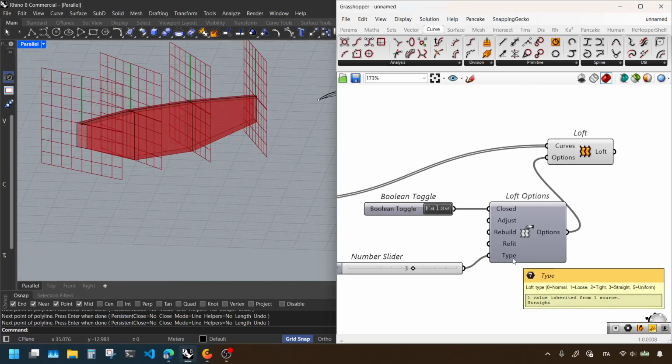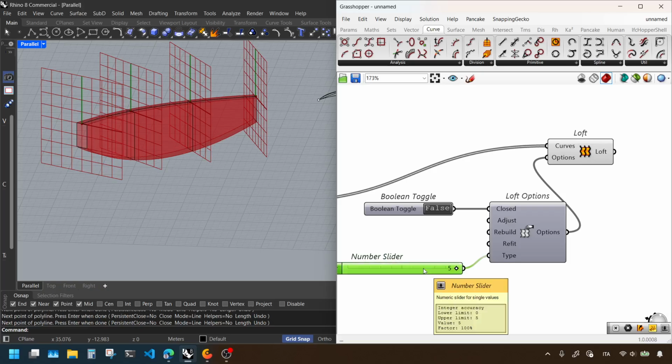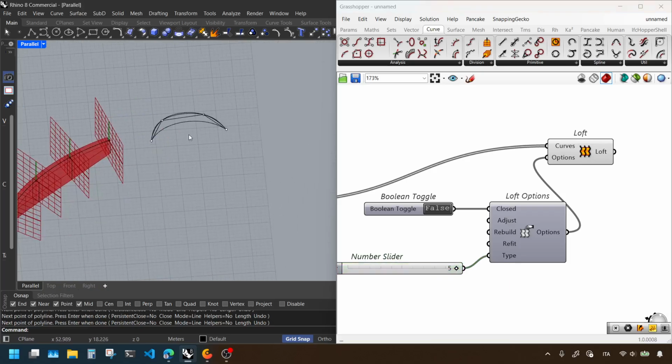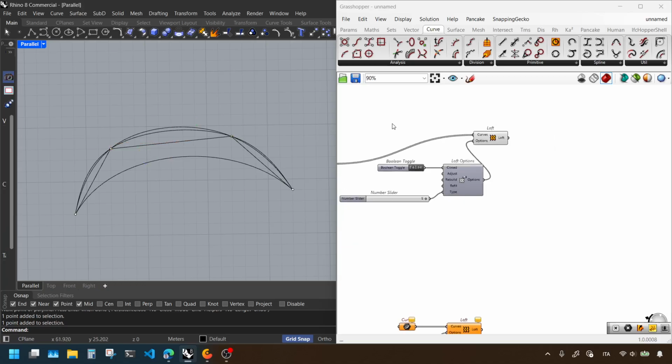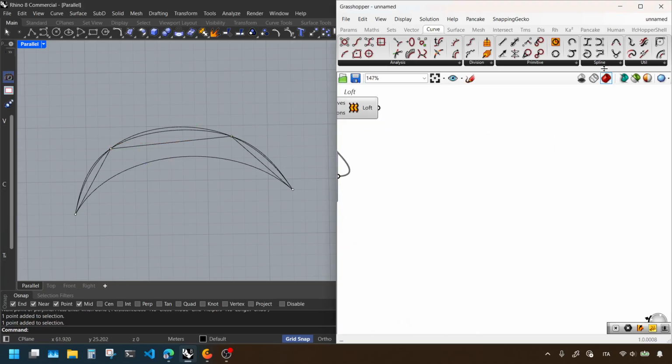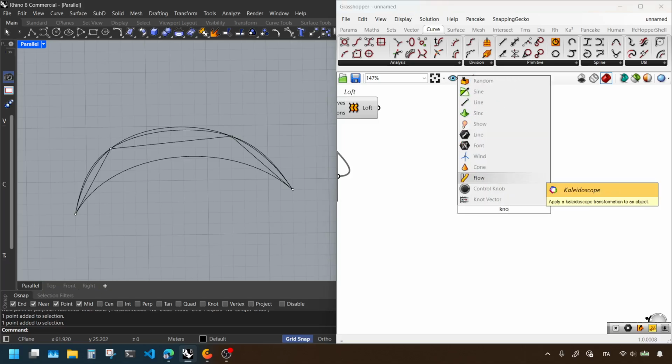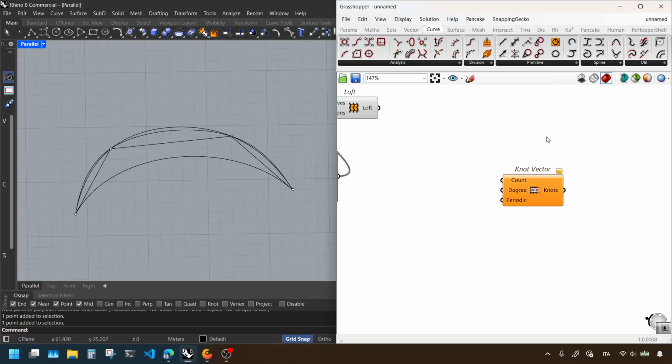And then you have the last one, which is uniform. And what uniform is doing is, it's creating a NURBS that is passing through the points. And after it does it, it normalizes the knots. So if you recall from last time, we discussed the knots briefly. So you can create a knot vector. And let's take a curve.